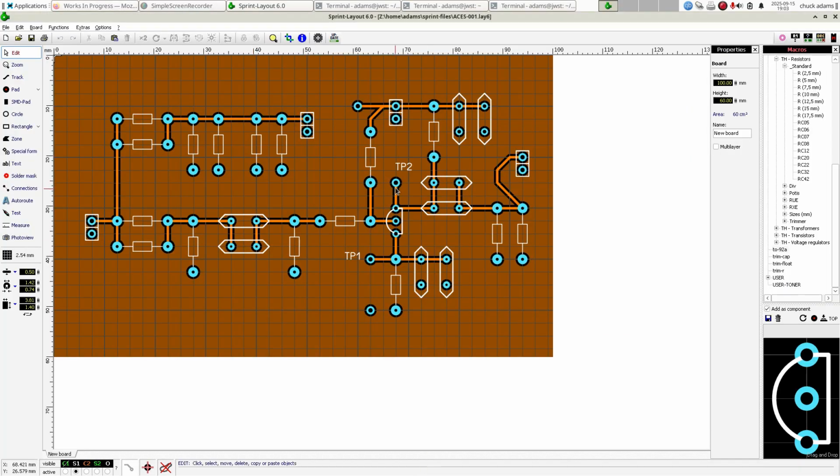But what I can do is I can put in some test points here and here. Just connect the collector to this test point. I'll put one of the pins out of a 2.54 header here. So I got this sharp pointy thing up on the top of the board, which I can hurt myself with. One here. If I measure this voltage, that'll give me the current through the 100 ohm.